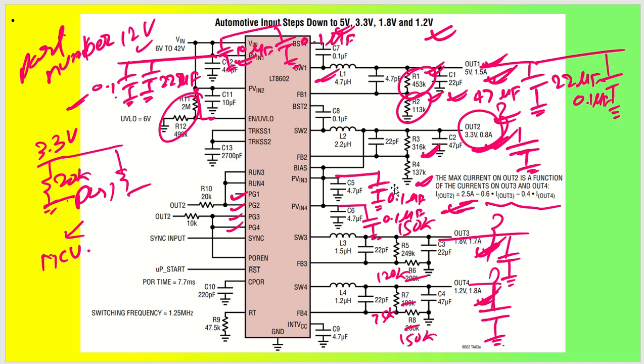Okay, so generally capacitor and inductor part numbers only will be required for you to design this particular schematic. Resistors are very easy to get. All the resistors can be taken in 0603 package. Okay, so all the resistors in 0603 package of 0.1 watt or 1/10 watt is more than enough to utilize.